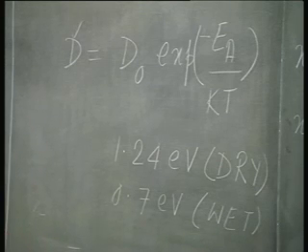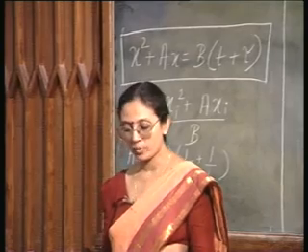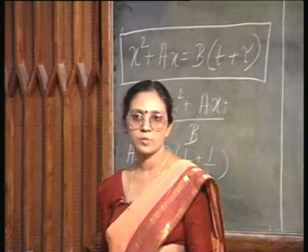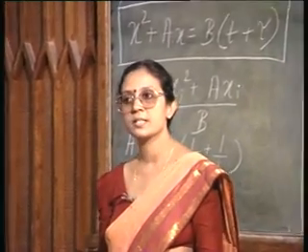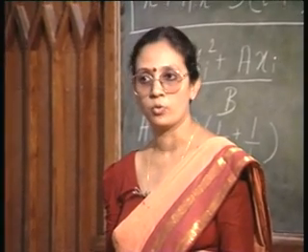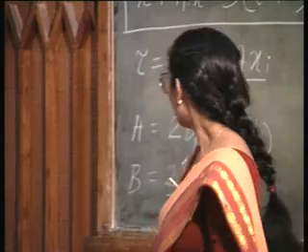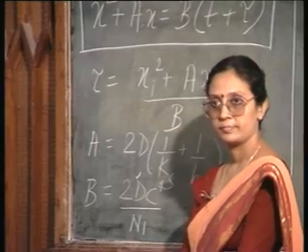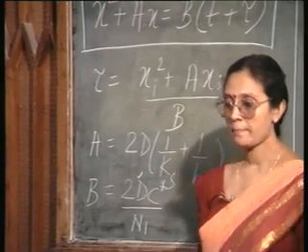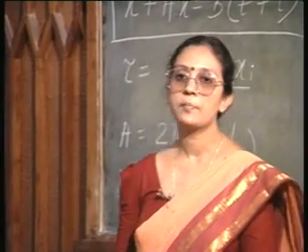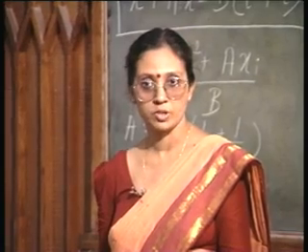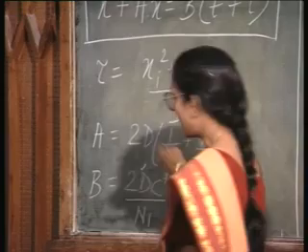Let us look at the linear rate constant B by A. B by A for wet oxidation at 920 degree centigrade it was 0.406 micrometer per hour, and at 1200 degree centigrade it has increased to 14.4. Now, what is B by A? If I look at B by A, see this D term will get cancelled. So, this increase in B by A with temperature is actually not because of the diffusion coefficient, it is because of these terms Ks.